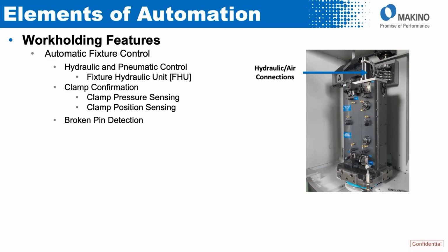You see in the picture that we have a rotary union attached to the top of the tombstone, and this is where we get the hydraulic and pneumatic connections from the fixture hydraulic unit into the tombstone and into the fixture for the control of that fixture.